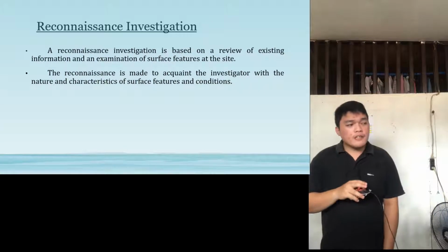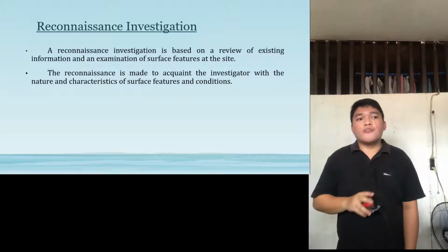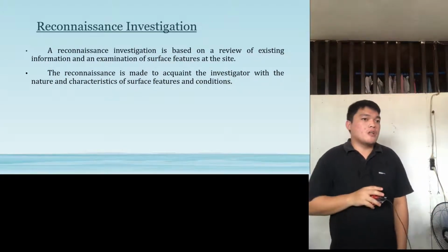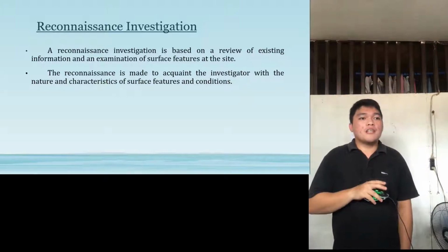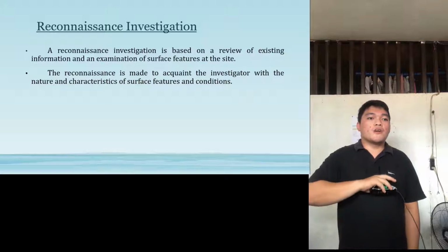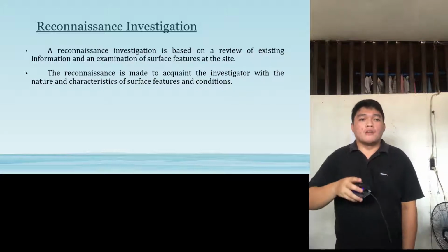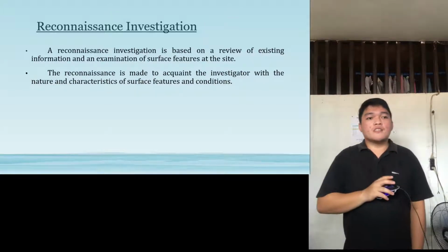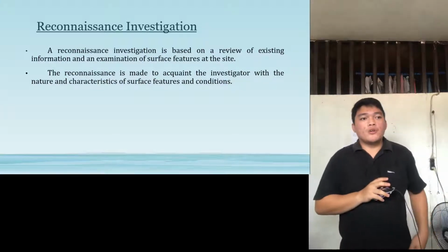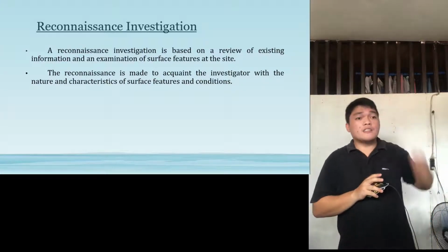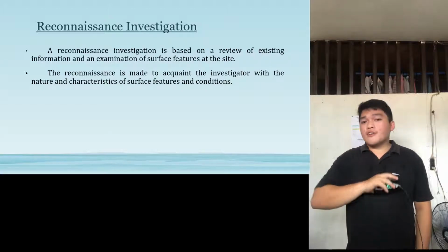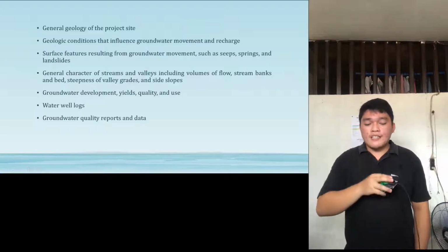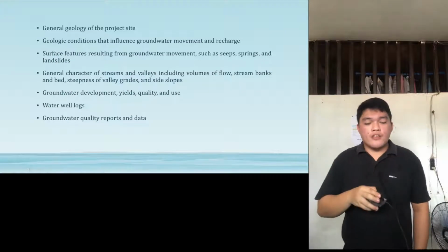So in hydrologic investigations, we have reconnaissance investigation. A reconnaissance investigation is based on a review of existing information and examination of surface features at the site. The reconnaissance is made to acquaint the investigator with the nature and characteristics of surface features and conditions. So in reconnaissance investigations, we can encounter these things.